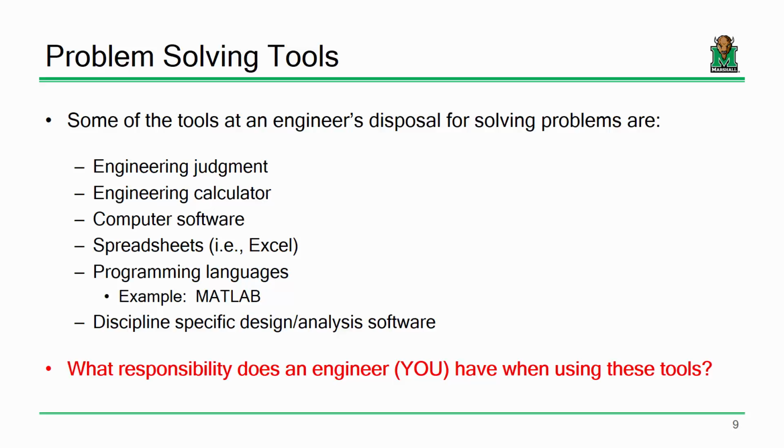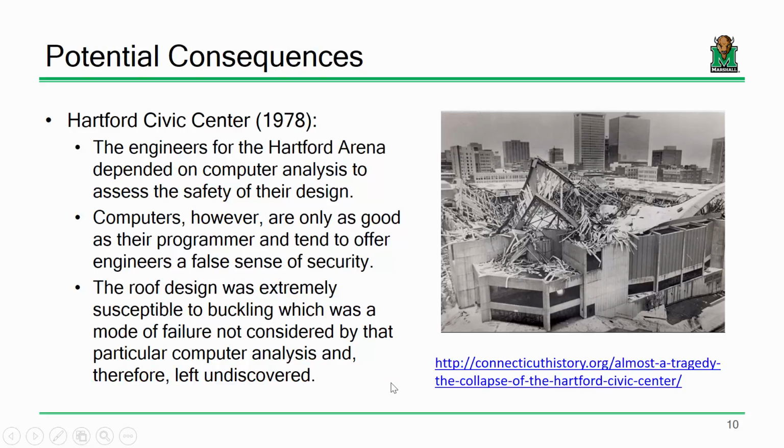There's a lot of computer programming in hydrology, and unfortunately, people make a lot of mistakes where they will use, for example, a rainfall tool that was developed for West Virginia, and then they'll apply that in Arizona. West Virginia and Arizona have wildly different rainfall patterns. And so you have to really understand how programs are intended before you can apply them. And that goes to all of these tools. All of the tools have limitations, and they have uses, and so you have to know what's the range of acceptable use when you apply them.